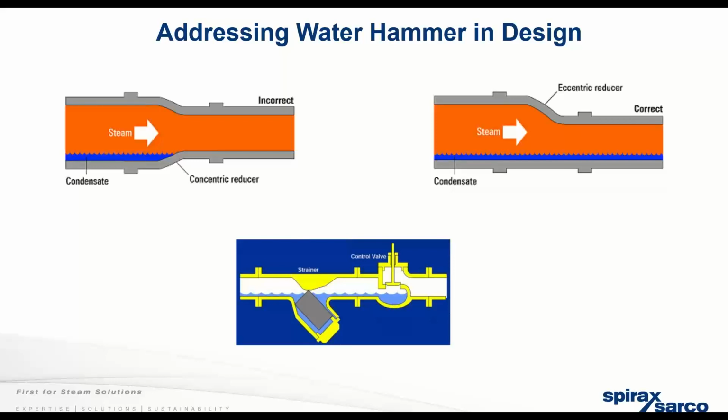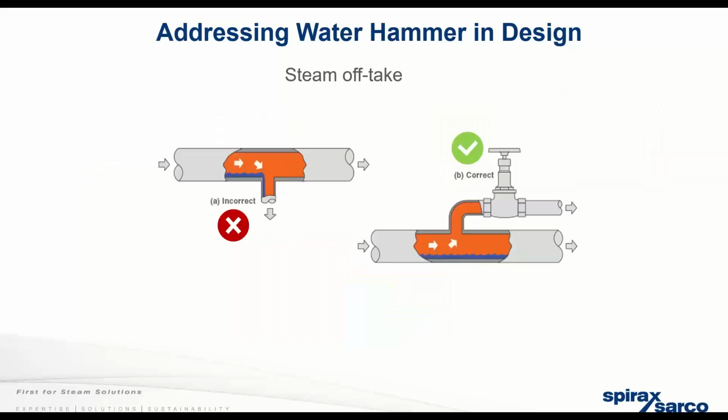So if we look at that picture and we roll that strainer on its side, we create a much more effective strainer, and we get rid of that volume of water in that strainer. And then if we get back to the impact pressures, because most of the time, even though we try to convince people to put that strainer on the side, we get to site and it's up and down. I like to make any strainer on the steam side made out of carbon steel, which at least gets me to the ANSI 150 class.